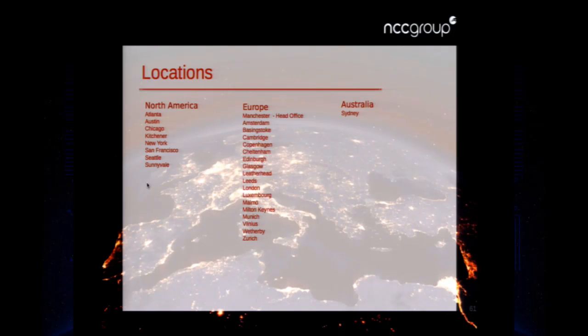You're shorting out the decoupling caps that you have issues with. Are you talking about shorting the decoupling caps out, shorting the ground on the high side? I tried doing some experiments like that on a device, and it wasn't quite successful. I'm not really sure why it didn't work, to be honest with you. In terms of doing a live attack, to short the power caps out, I just think the circuit wasn't made like that. It's definitely a lot easier to target a voltage regulator supplying the power, because it might be connected to multiple lines depending on the device that you have.